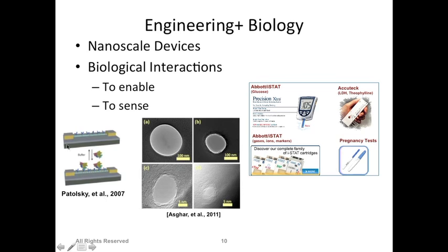And this is one example of how we can use carbon nanotubes to develop sensors. This component can be considered a transistor. You have a source here, you have a drain, and you connect the source and drain with a single carbon nanotube, and then you functionalize it.